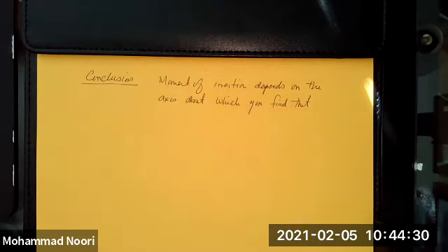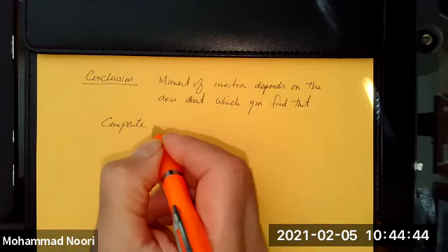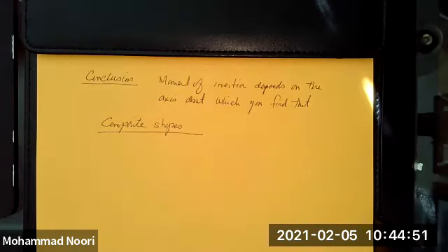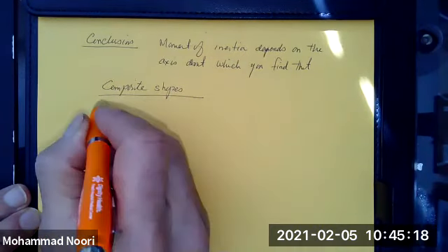We are mainly interested, let's say, in case of moment of inertia, like centroid, in composite shapes, right? Because for the most part, in structural mechanical systems, the kind of structural components you consider have cross-sectional areas that, if they are not just simply made of a simple geometric shape, circular or triangular or elliptical, would be of shapes that are basically of composite form.